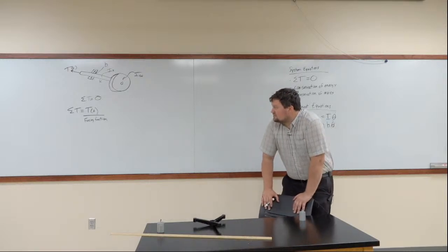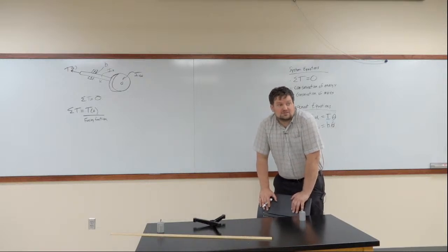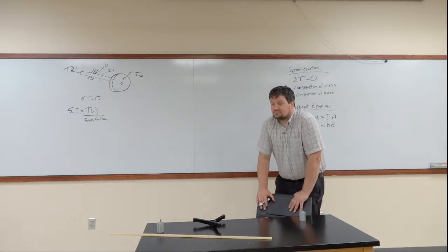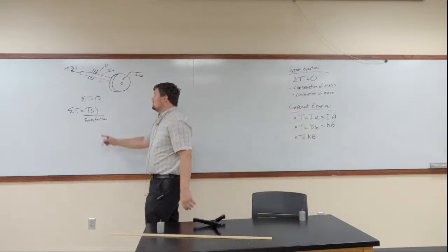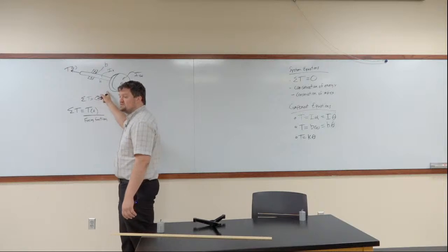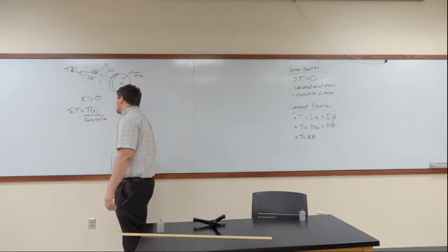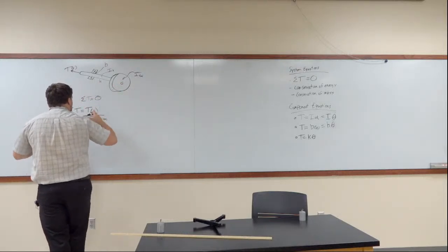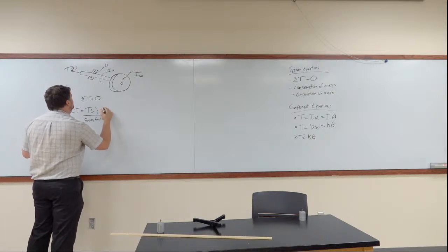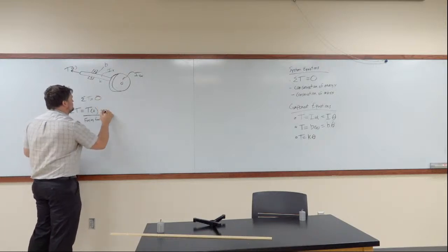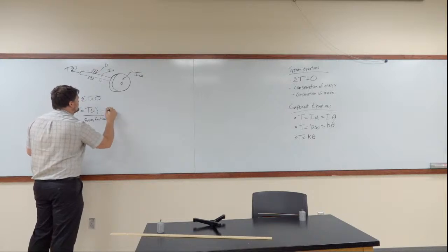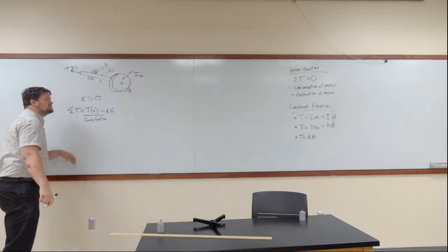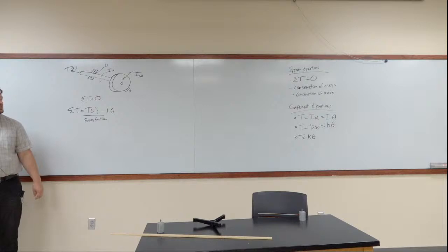What other torques do we have? It's the torque of K times theta. We're going to have some amount of torque, some amount of energy that's consumed by the rotation of this shaft. And that is mounted directly to here, so we do have a minus K times theta, where theta is represented by the rotation of the end of the wheel.